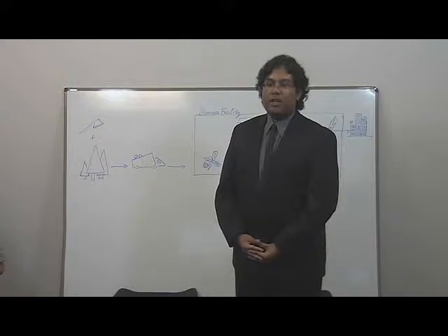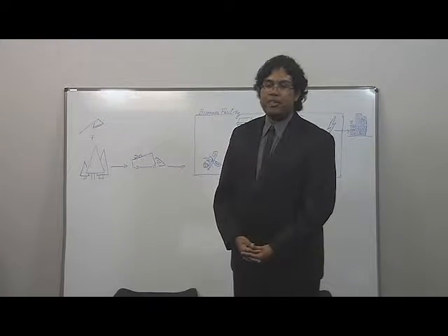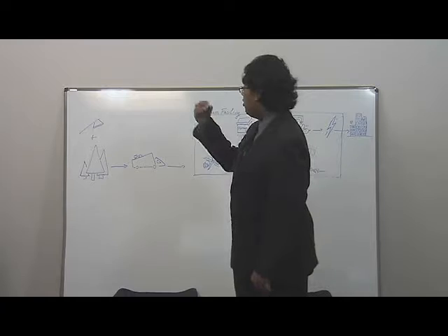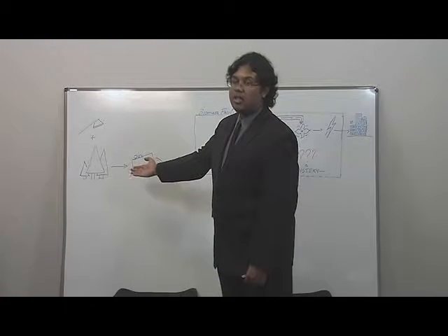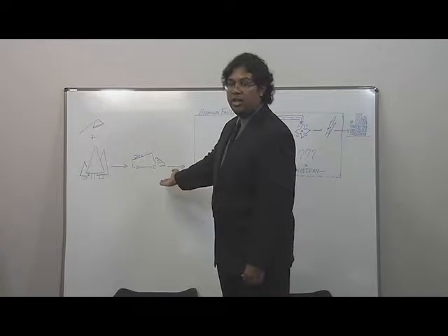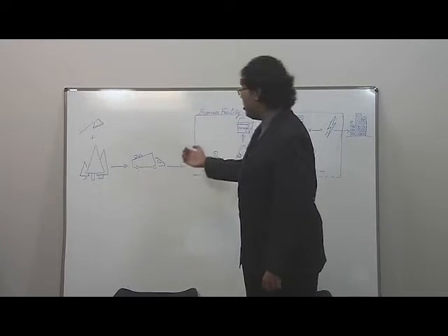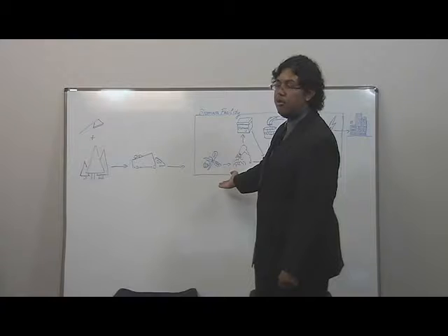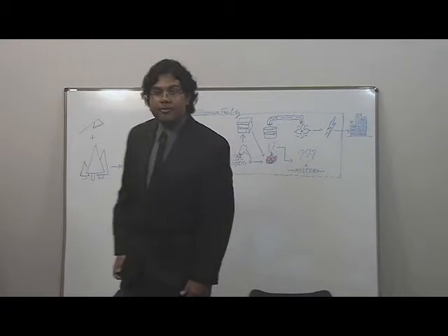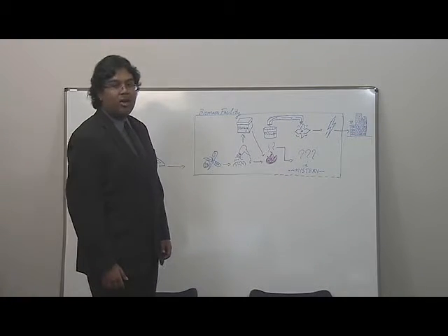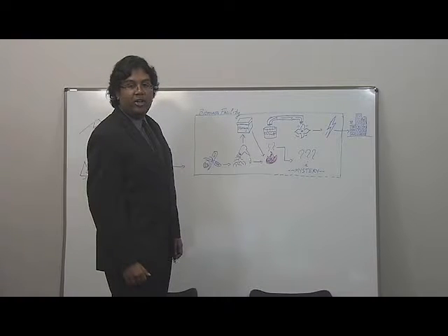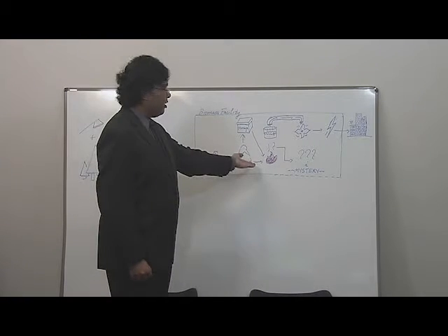Let's step through the direct combustion process used to harness usable energy from wood. First, trees are harvested, or wood debris is collected. It is transported to the facility where it typically undergoes a pre-processing step. It may be size reduced or dried to reduce moisture content. From there, it is stored or fed directly to the furnace.